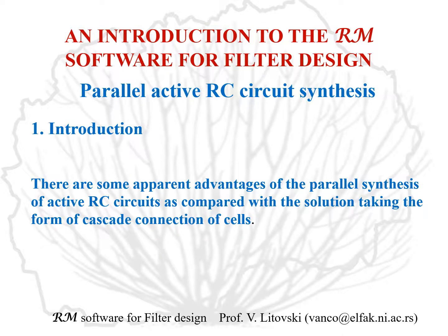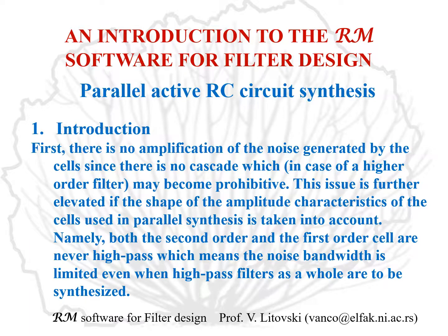There are some apparent advantages of the parallel synthesis of active RC circuits as compared with the solution taking the form of cascade connection of cells. First, there is no amplification of the noise generated by the cells, especially input cells, since there is no cascade, which in case of higher order filters may become prohibitive.